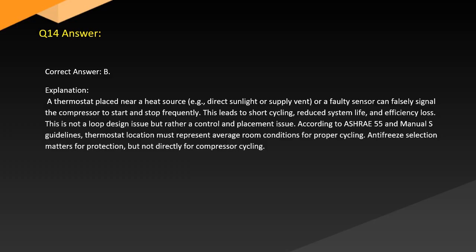This is not a loop design issue, but rather a control and placement issue. According to ASHRAE 55 and Manual S guidelines, thermostat location must represent average conditions for proper cycling. Antifreeze selection matters for protection, but not directly for compressor cycling.